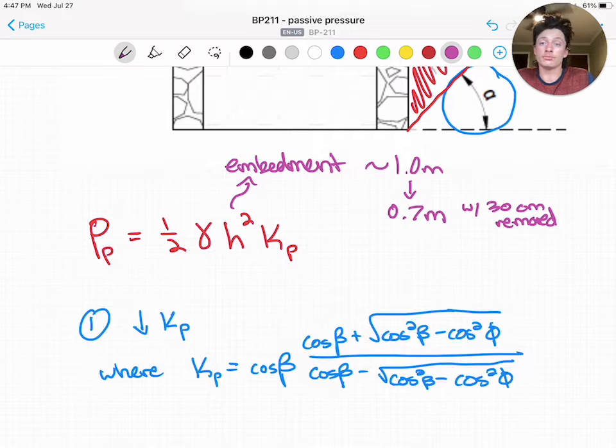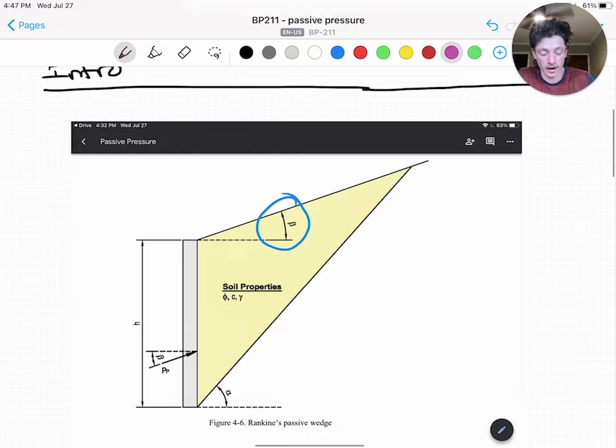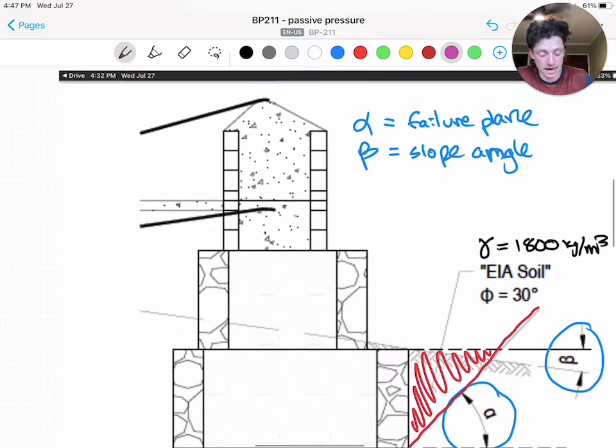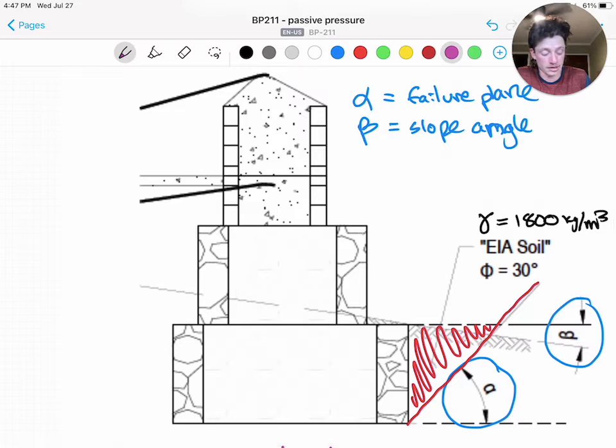And also, before we move on and just use this equation, it's important to use some engineering judgment here. So the passive pressure is relying on a soil wedge. Shouldn't that be reduced as the soil slopes away from a foundation? And remember, we looked at these two different situations from above, the screenshot from the Caltrans manual, and then what is actually happening with the slope, the beta value sloping away from the foundation.